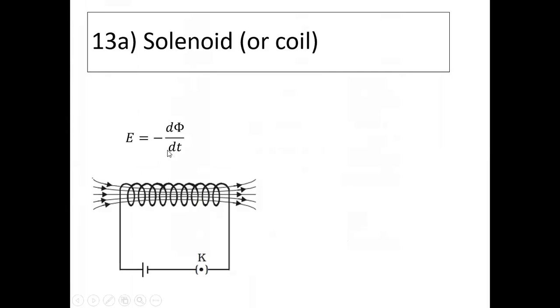Right? So we are just basically using Faraday's law. EMF is induced if there's a change in flux. We call it self because it is on the coil itself. And then remember, your flux linkage is just BAN. Right? The field due to the coil times the area of the coil times the number of turns. And then your B, for a solenoid, is mu naught N times I. So if you want, you can put all these inside this equation. That's what we are going to do.